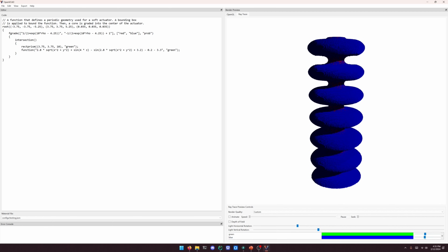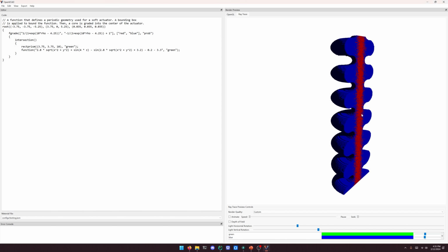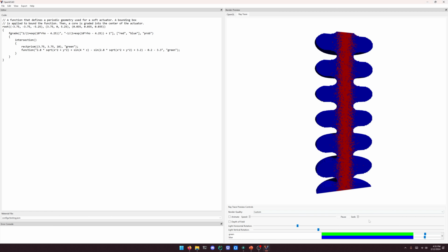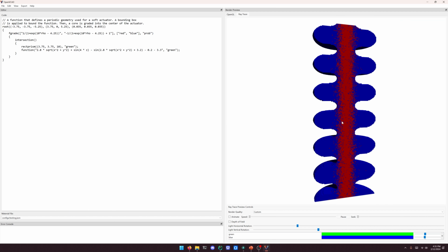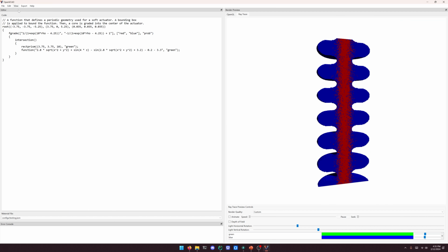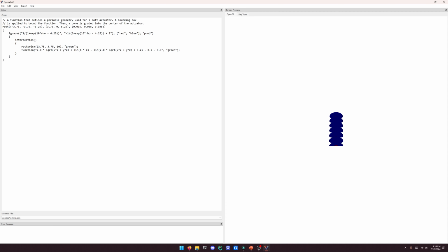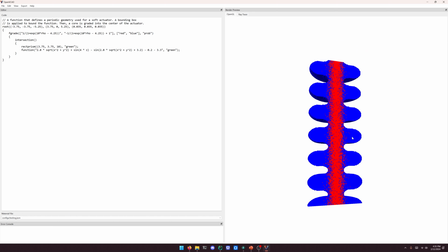Let's say we do want to take a cross-section through. All we need to do is just sample this and stop short on one of the axes. So I could set this to 0. I can render with ray tracing again. Now we can see a cross-section of what's going on through here. If we zoom in, you can see we have some transparency, and we're kind of viewing at that mixing core. This also works for rendering the voxels the traditional way without the GPU, and we can visualize.